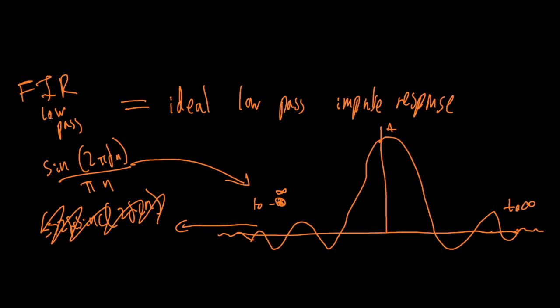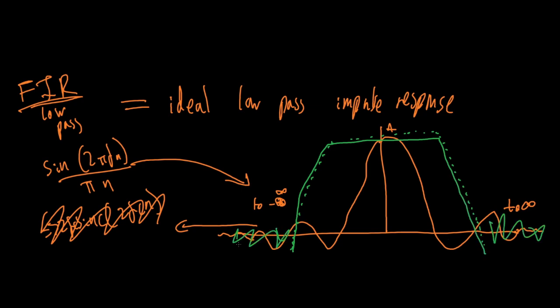But remember, with FIR filters, we are finite in nature. We're not going to let this go on forever because that will be too computationally expensive. So we restrict it, and we restrict it with something called a window function. We are only accepting the impulse response up to here. So by applying a window function, all you see is this. You don't see any of that. And this is what gives FIR filters their finite nature.